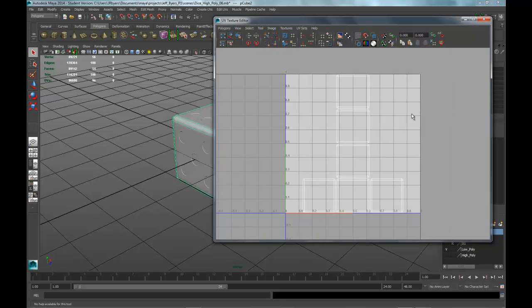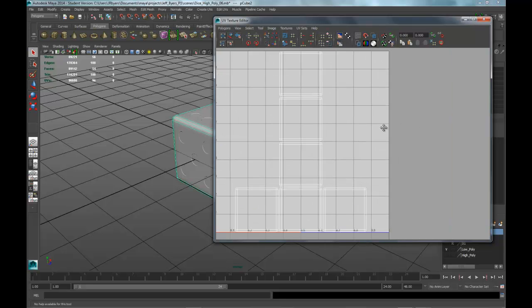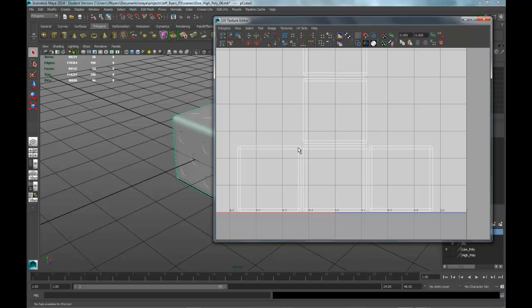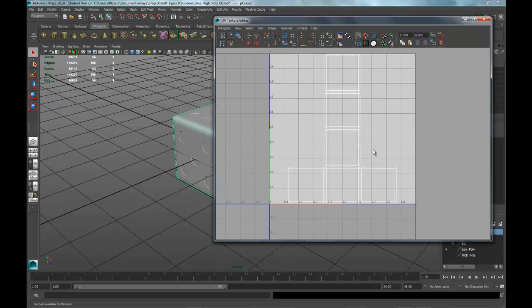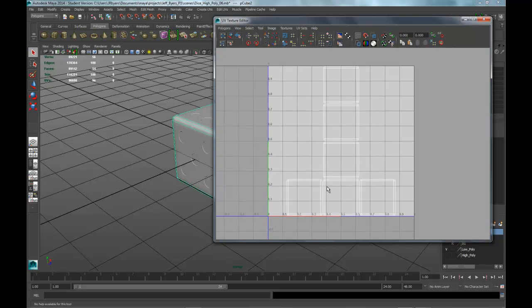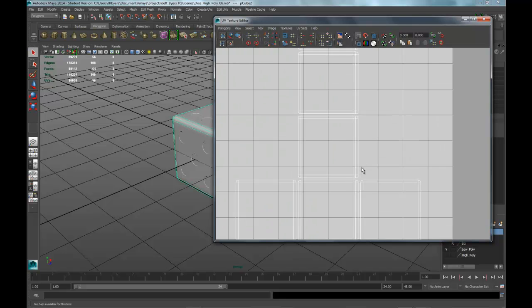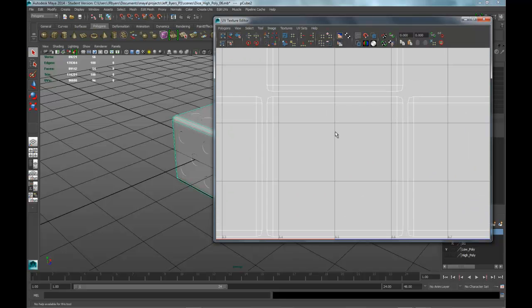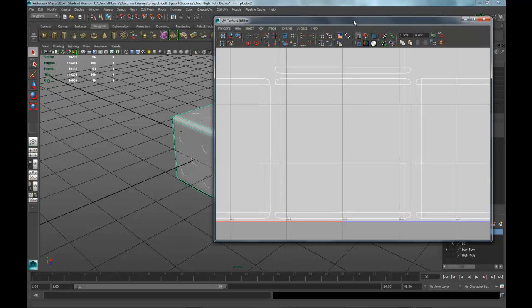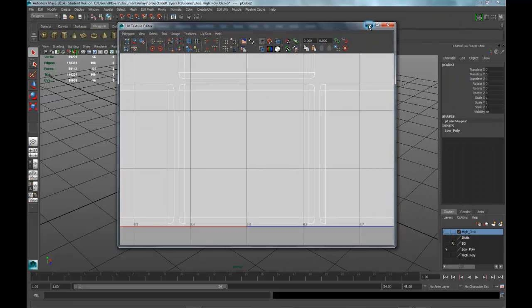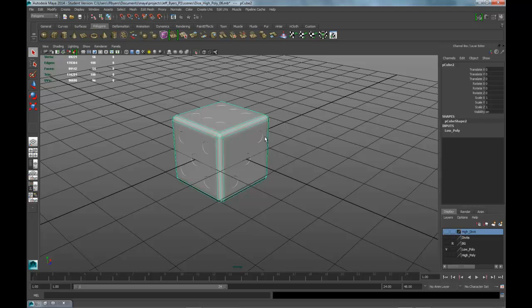It is UV mapped, but I need to merge, move and sew the UV, so I'll do that before, and then I'll have to export it again if I want to keep the seams few. The fewer the seams, the better. I'll do that, and anyway, we'll go into XNormal and pull the alpha and normal maps, or ambient occlusion and the normal maps.